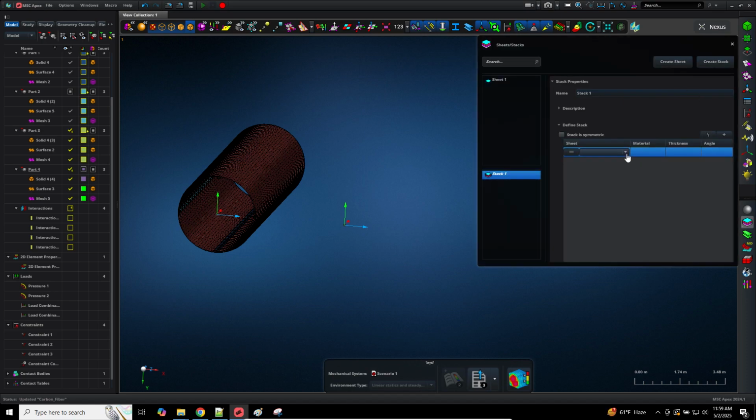Now what I'm going to do is the following. Eventually we want to use angles of 90, 45, and so on and so on. But just so you know, the stacking direction, I'm going to give this an angle of 1. Or actually, there we go. So let me create a few layers here actually. Let me create 8 layers. Oh, and a quick comment here.